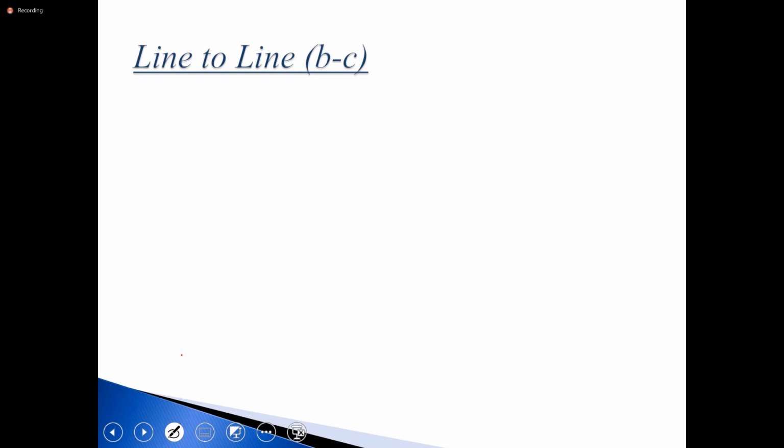You will look at three-phase faults using your lab exercise. So here we have both lines coming in contact with each other. What will be the boundary conditions? B and C are now in contact. What facts do we know? Sure, VB is equal to VC. Okay, so that's the first one. In terms of the voltages, B is equal to C. Good. Next, what else do we know?